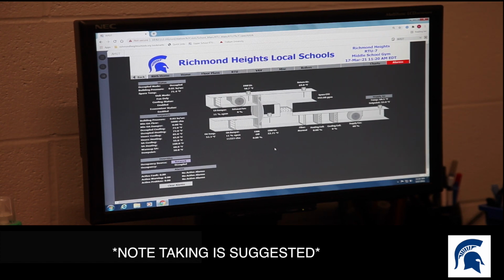And then you can hit the clear alarms button that's on the graphic here, right below where all the alarms are at. And I'm gonna make a change to how that button works on the back end side so that it doesn't do what it did during the first training session. You can click that button and it'll reset all the alarms, and then the unit will try and fire back up. And if it fires back up, then you're good. If it trips an alarm, then you know, hey, somebody needs to go mechanically look at this unit and make sure it's working the right way.